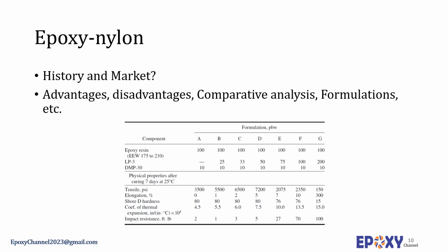Epoxy nylon adhesives are generally available as unsupported film or as solvent solutions. Adhesive films are made either by solution casting or by dry mixing and calendering. Common solvent solutions are blends of methanol, water, and furfuryl alcohol. A curing agent is 2,4-dihydrazino-6-methylamino-s-triazine. Other suitable catalysts are dicy and aromatic polyamines. Typical formulations are shown here for your reference.